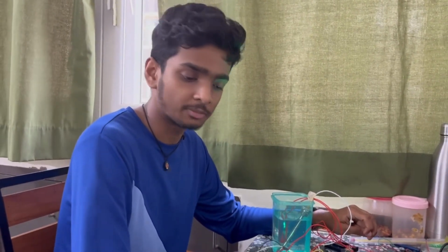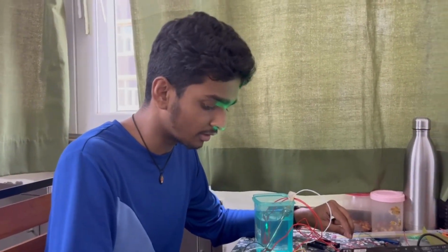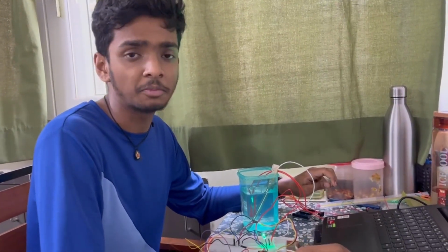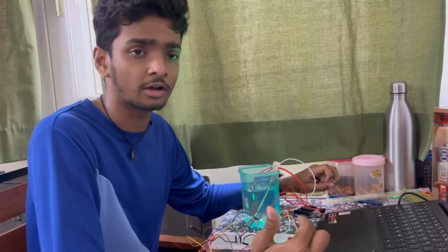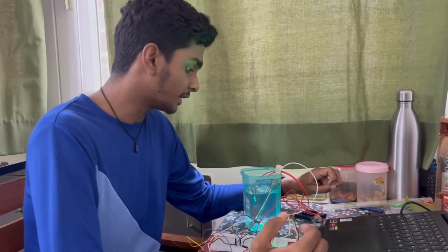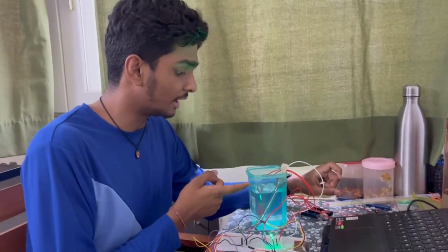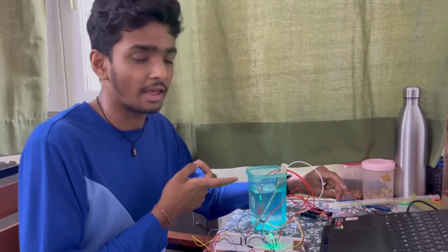Here, I will be telling you all the challenges we faced while working on this project. For the relay module, it was a tedious task for us to know how it works, the input pins and the output pins, and how to connect it across the heating element. The second challenge we faced was with the RTD sensor. We had to find the data sheet, and then find the conversion formula from resistance to temperature to get the temperature reading.